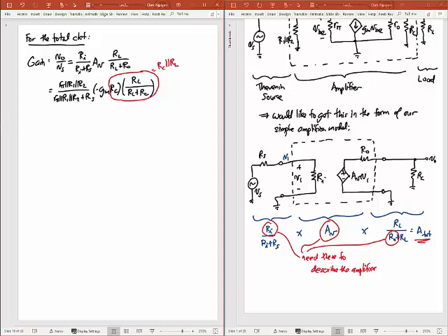So that means I can rewrite this whole thing, the gain, as just being equal to, moving the minus sign to the front now, still this R pi parallel with R1, parallel R2 over R pi, parallel R1, parallel R2 plus RS times GM, but now times that parallel combination of RC and RL. So that's my equation for the total gain from Vs to V0.